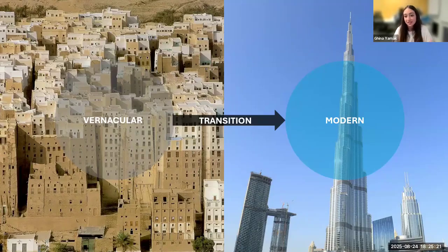On the other hand, modern architecture in the Gulf is introducing new drivers and challenges. The urban growth, the high-rise towers, iconic designs, and globalized aesthetic meant facades now had to meet much higher technical demands. Tall glass curtain walls, complex geometries, and high-performance cladding systems are visually striking but require careful engineering to address extreme solar radiation, high ambient temperature, dust, and humidity. So facade engineers must now optimize thermal performance, reduce cooling loads, and prevent thermal bridging while ensuring durability in harsh conditions where materials can degrade quickly.